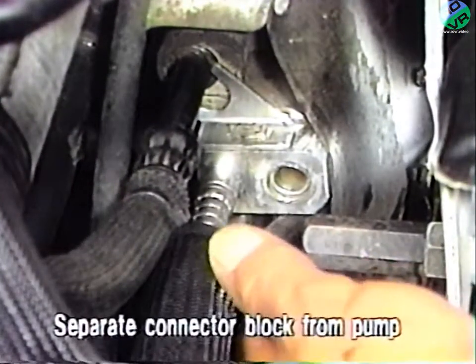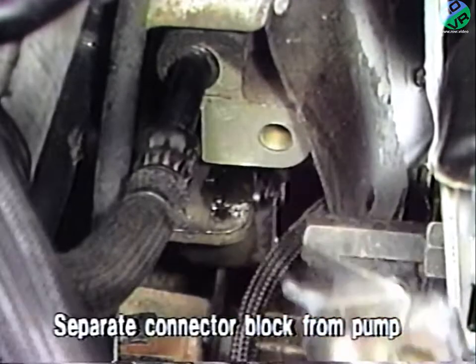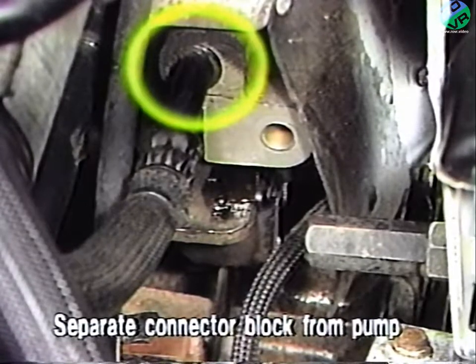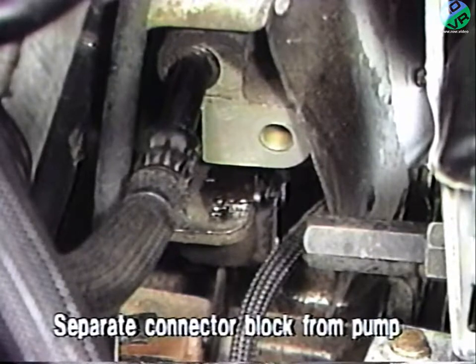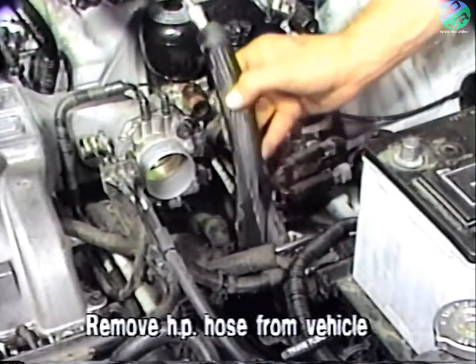Next, separate the connector block from the pump and motor assembly. When performing this step, be careful not to disturb the pump end of the other low-pressure hose. The low-pressure hose is only retained by the internal O-ring seal. Now, remove the high-pressure hose from the vehicle.